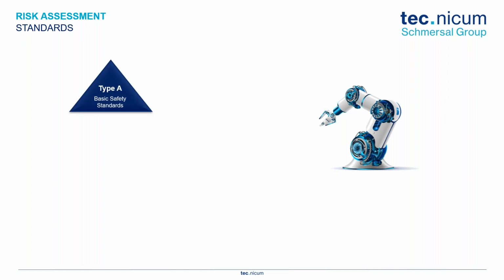So we look at the standards. They can be broken up into 4 types. And type A is a basic safety standard, like the risk assessment standard. It's basic. It's giving us the fundamental steps, right? It's giving us the definitions of the risk assessment, definitions of a hazard and a risk. It's giving us some guidance on what to look for as far as the probability of a risk. It's a basic standard to give us some guidance on a risk assessment.